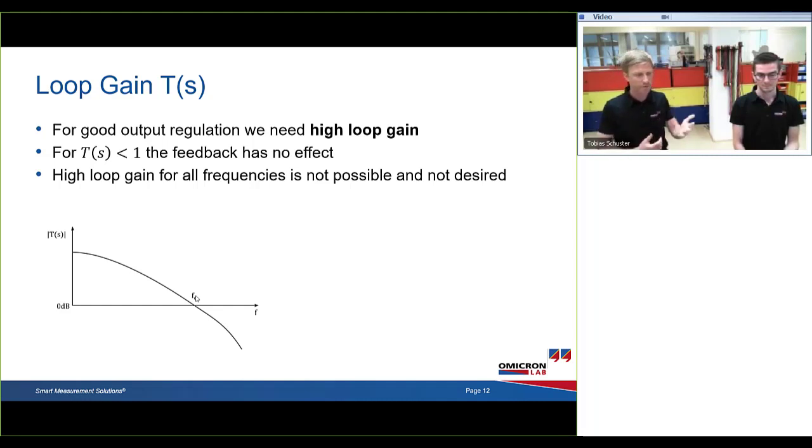At low frequency there is high gain, which is normally also limited by some maximum gain limit. And then it starts to fall, and it passes through the FC, that's the crossover frequency, and then at higher frequencies normally the gain is even further attenuated by placing an additional pole somewhere at half the switching frequency or something like that.